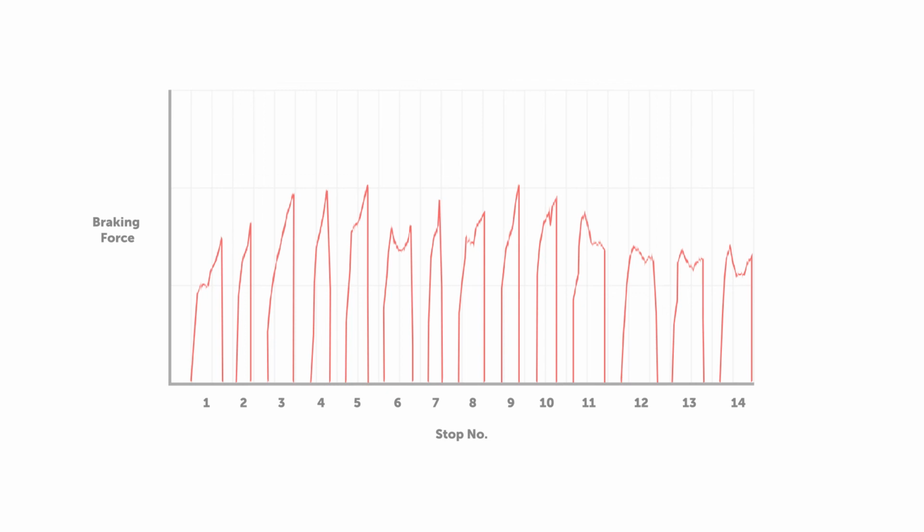Since the brakes are starting from cold, we can see that the first few stops show the cold performance of the pad. Once the brakes have heated up to their operating temperature range, it's possible to see how much friction they can generate, but also how the friction varies throughout the stop, as this has a dramatic effect on the feel of the brakes and how easy they are to use.